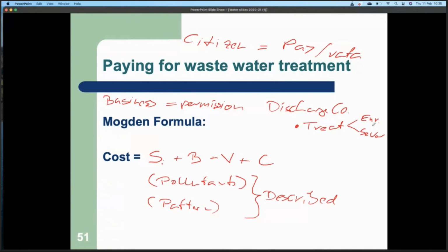So there's absolutely no rule that says that business wastewater needs to be discharged into sewer. As a business, you can decide to treat all your wastewater to a standard that is the same as what the local water company would achieve, and discharge it into the environment. The problem with this is that then you're not dealing with the wastewater company as your regulating authority, but with the environmental regulator.